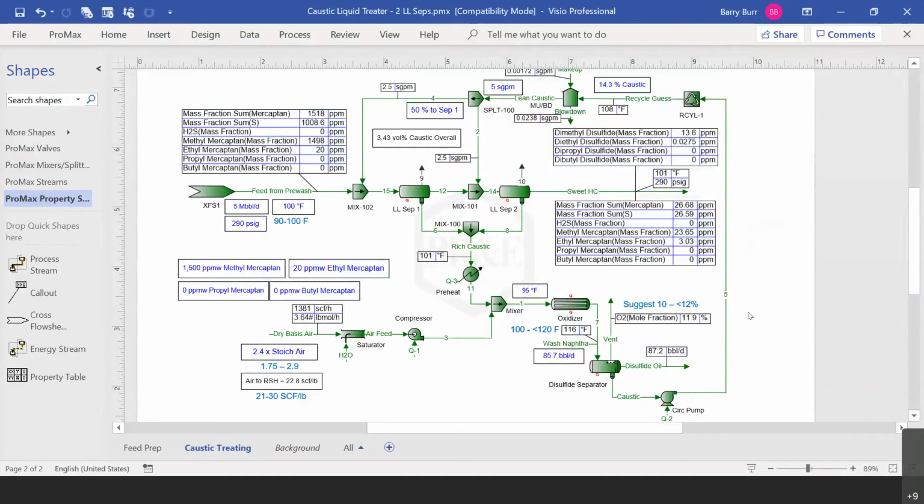Okay, here is the other common style of mercaptan removal system that we see. This is a very, very similar process. It's really the only difference that I can identify is that instead of there being a liquid-liquid extraction column, that equipment has been replaced by two liquid-liquid separators. And if you noticed in the liquid-liquid extraction column I showed earlier, there were only two ideal stages. So it's very similar to this because here we have, once again, two ideal stages.